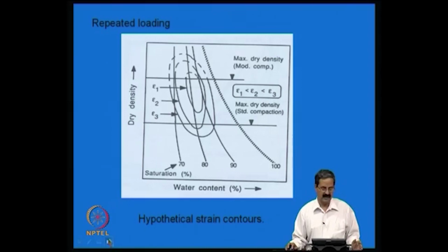If you are trying to understand any of the phenomena like rutting and fatigue in pavements, strains are very important. The moment the strains develop, you will see the formation of ruts, then after that it leads to potholes and all that. So, you do not want that. That is the reason compaction has a very big influence in the case of pavements. Of course, for all geotechnical structures it is very important, but some of these things will be very evident in the case of failures in pavements.